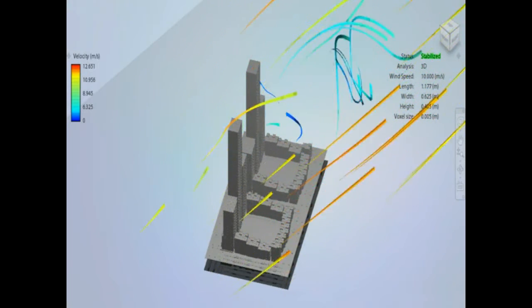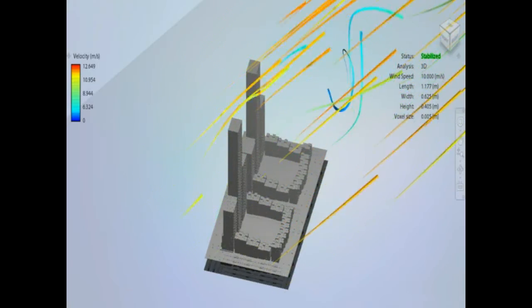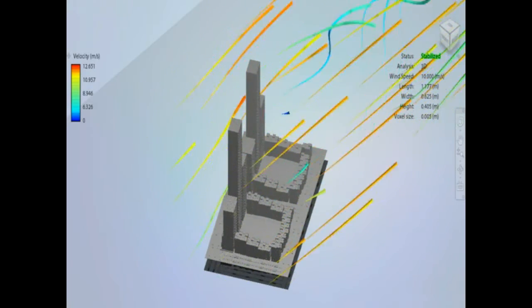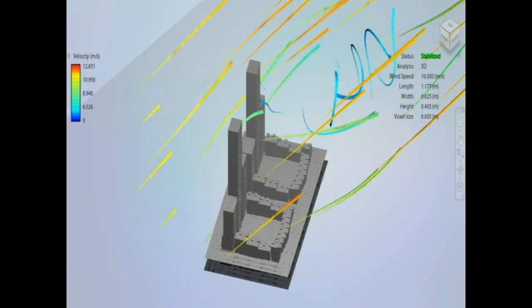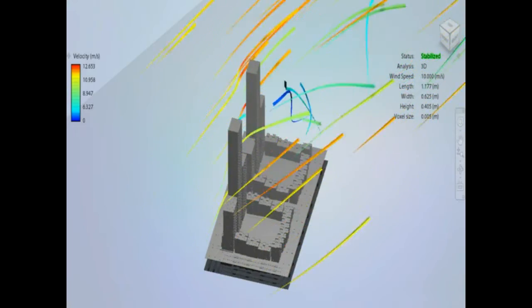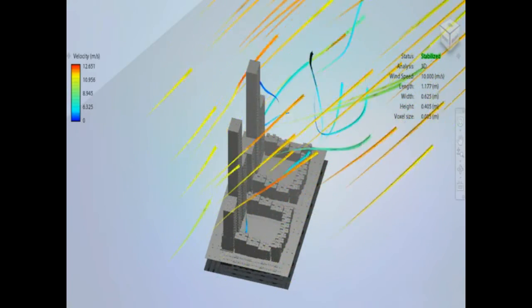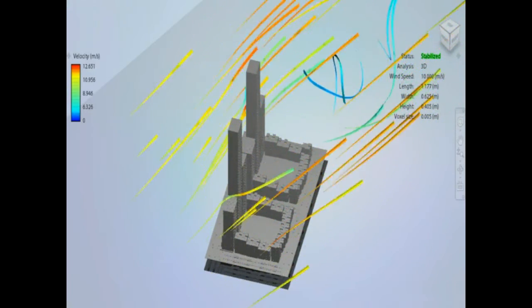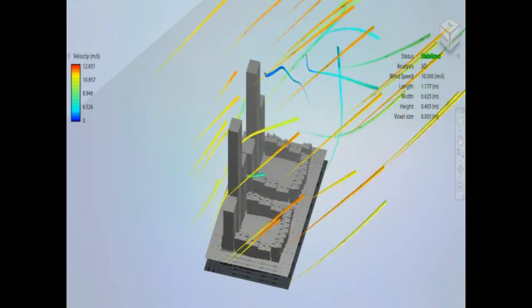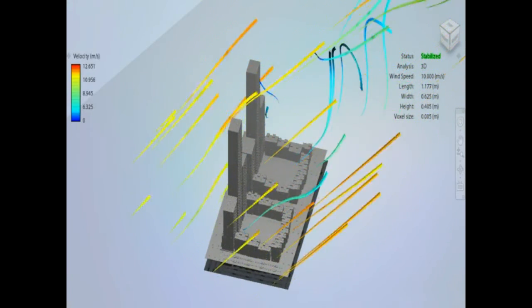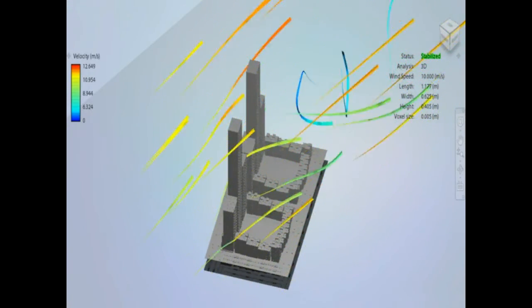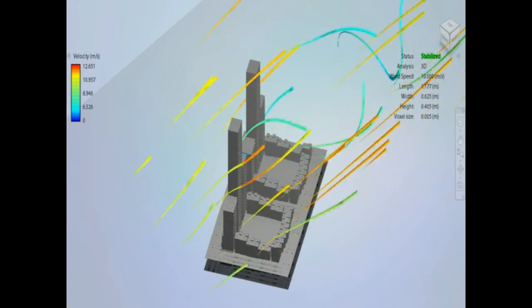The wind analyses show that the area generally feels comfortable with regards to the wind. Wind speed below 8.3 meters per second is generally considered to be comfortable for walking. As per the design principles for designing against the wind, the buildings have variable heights. The angles and space between buildings are appropriate to allow the wind to disperse.